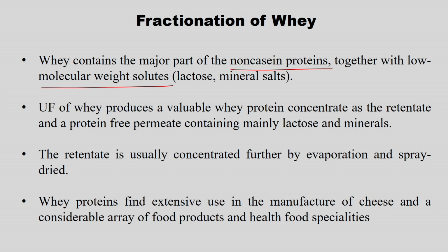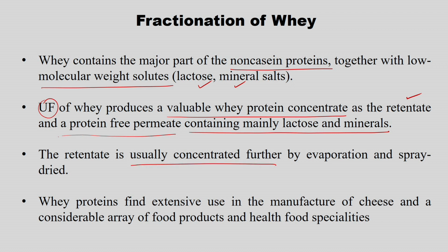So, ultrafiltration is used to fractionate the whey into a valuable whey protein concentrate as the retentate, and the protein-free permeate, which contains mainly lactose and minerals. The whey protein is concentrated, so the retentate is usually concentrated further.